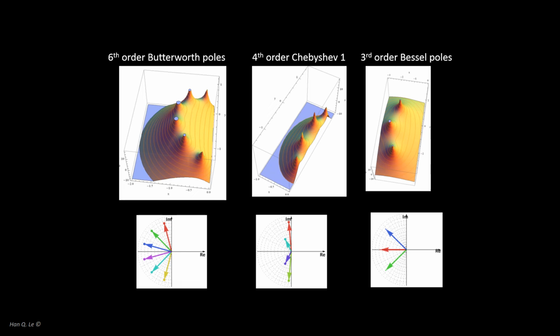The spatial arrangements of the roots are to design different frequency response behaviors, usually the trade-off between the sharpness of the cut-off edge versus the residual ripples of the output magnitude versus frequency in the passband. The circuits of Lab 6 are the simplest possible as each filter has only 2 roots, the minimum number required for a complex root filter. It should be noted that a first-order filter, such as those in Lab 5, can only have a real root.